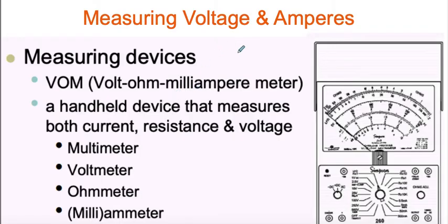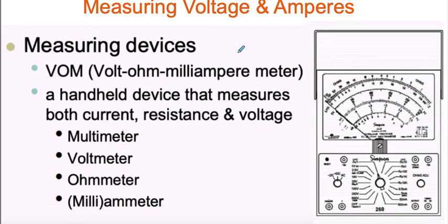Okay, so here's a picture of a volt ohm meter. So we can switch these. You can switch them from volts to amps with the proper settings. You can find the resistance in a system. So these are all kind of built into one machine, and these are pretty nice. If you wanted to ever measure the voltage in your battery, maybe your car's not starting or something like that, it might be nice to have one of these. They're like 10 bucks, pretty cheap. And remember, measuring voltage, you could just put your test probes on 2 points in the circuit, so it'd just be positive and negative on the battery, and you can test the voltage going through the battery.